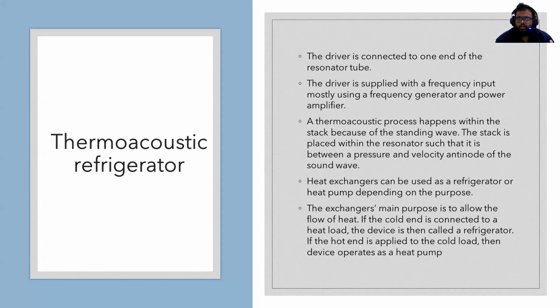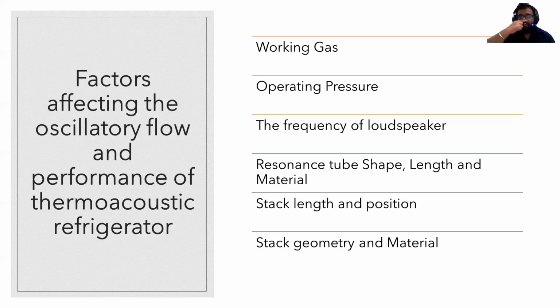A thermoacoustic refrigerator has four parts: a driver, a resonator tube, a stack, and a heat exchanger. A driver is connected to the resonator tube and is tasked to supply the frequency input, mostly using a frequency generator or a power amplifier. The next part is the heat exchanger, which gives a purpose to the thermoacoustic refrigerator by making it either a heat pump or a refrigerator. The stack acts as a heat gradient for the thermoacoustic refrigerator.